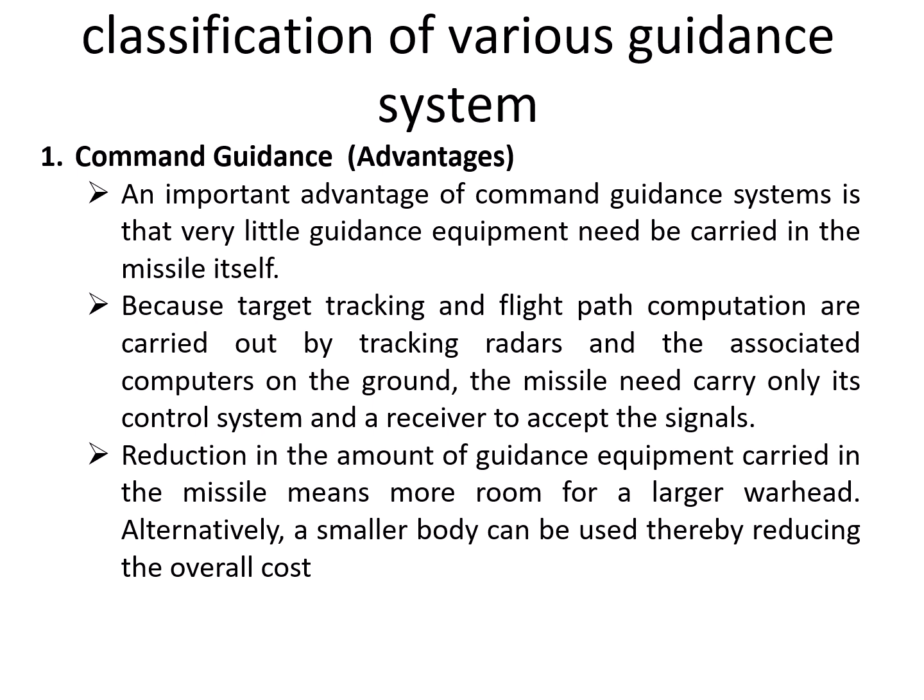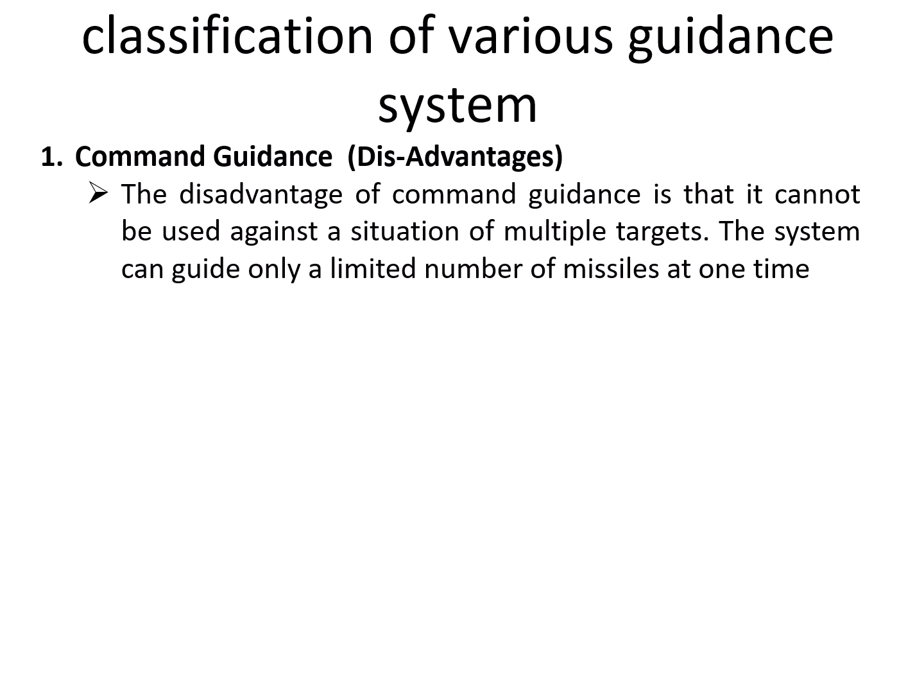The ground station will be locating the target and sending the location, and according to that your command or steering signals are produced, so lightweight missiles can be produced, or more payload can be attached, and a smaller body is fine. Another point is that it cannot be used against multiple targets, because every time a single target needs a single line of sight, and every time you need to produce a steering command for that. Again, your command signals are from the ground station, so there will be a lag in the communication, a delay in the communication, and that will be the disadvantage in this case.